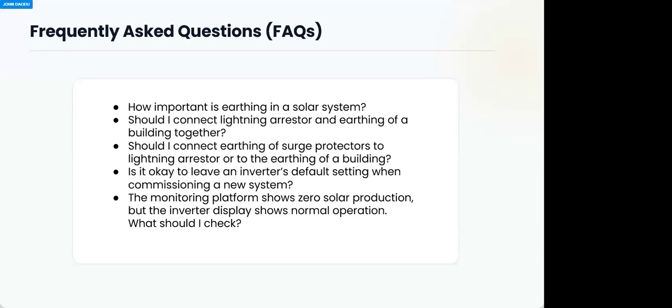Time. There is a clock in some of these inverters. If you don't set the clock, it will be there. Battery level and battery shutdown, if you don't set them properly, you can over discharge the battery and get the battery damaged within a short time. And then they will tag your installation as, maybe the battery is bad, it's a fake battery, or the inverter is not working well, because you install and within 2 weeks the battery is having problems. So you need to put all these settings in proper position. It's very important. So I think that answers that question.